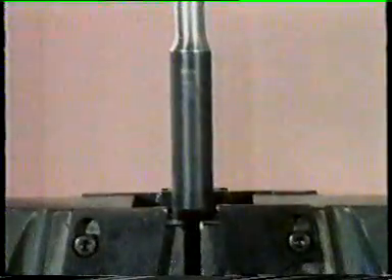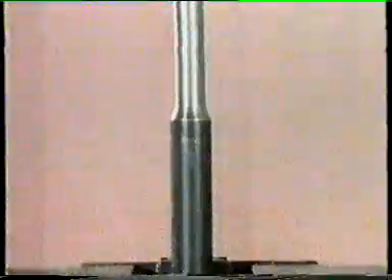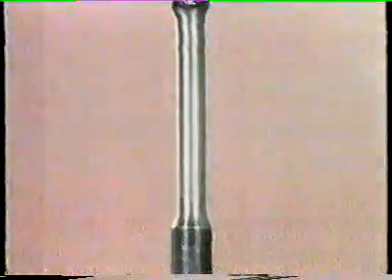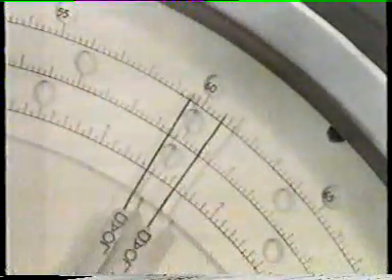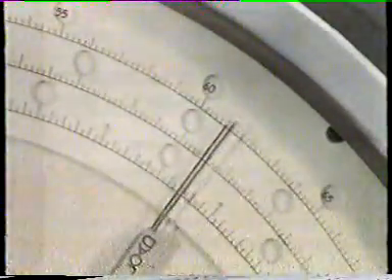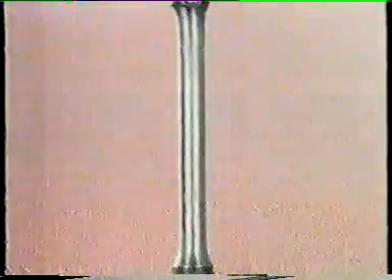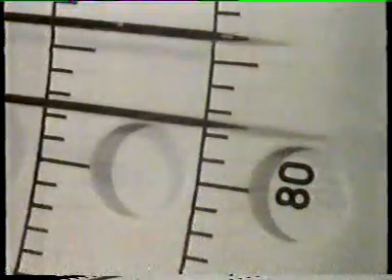Let's see what force is needed to pull this one apart. This test piece has the same dimensions as the previous one, so by comparing forces, we can compare the tensile strength. Well, that's where the 0.1% steel fractured. Increasing the carbon seems to have increased the tensile strength. Nearly 80 kilonewtons this time.